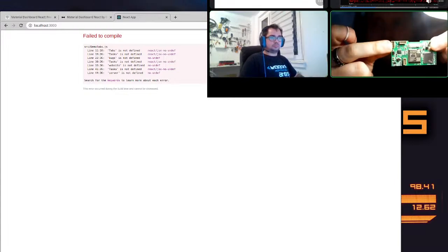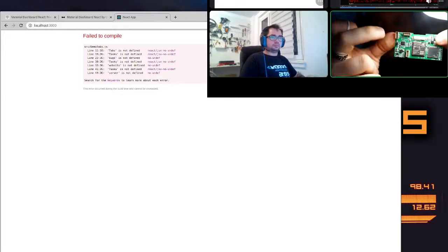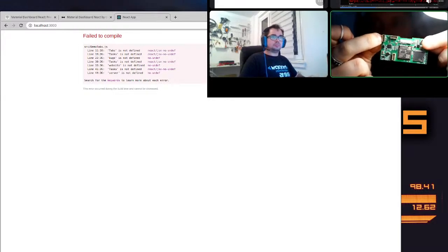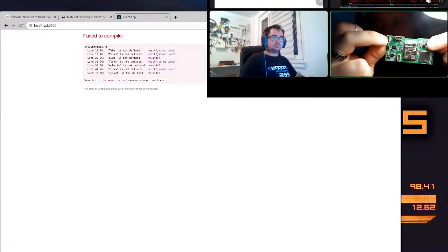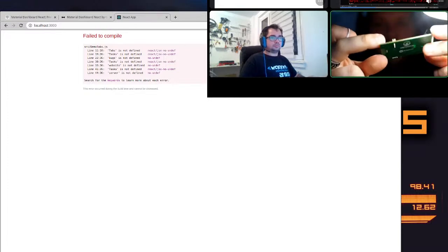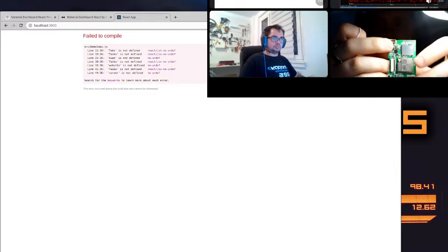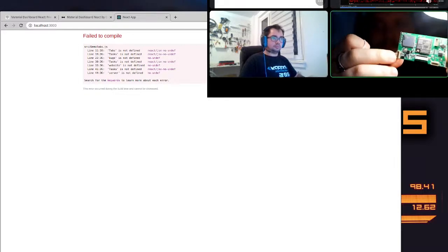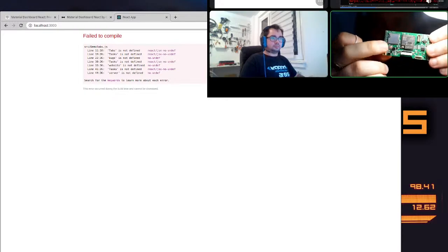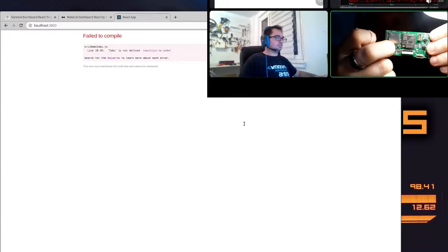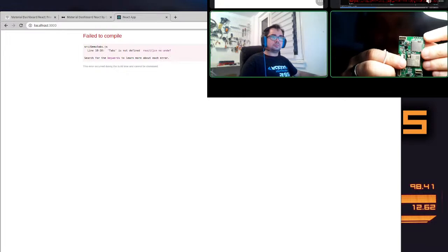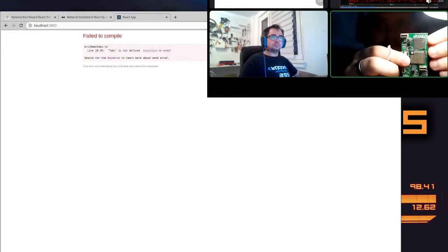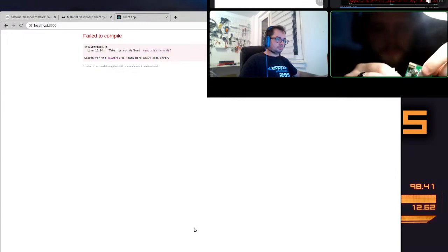And that's the encoder bit, so you can actually put an encoder in there. That's what I'll use as GPIOs, those two. And one of them, called EC, is actually the button that we use to change the screens and stuff like this. The boot button, which lets you boot the device to flash it. This is like an FTDI type header thingy. You just plug it in.